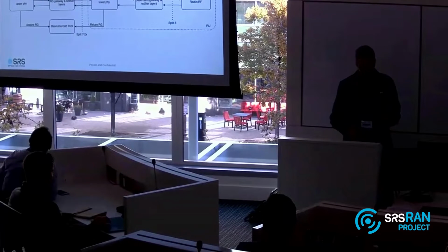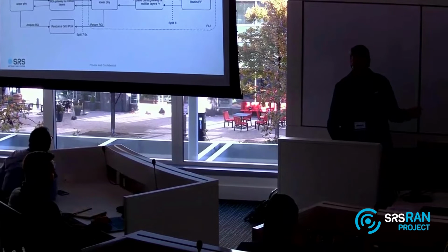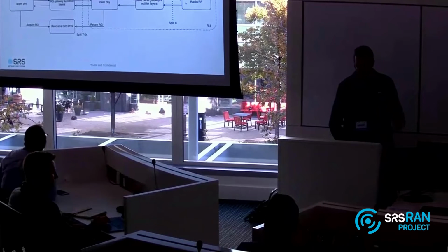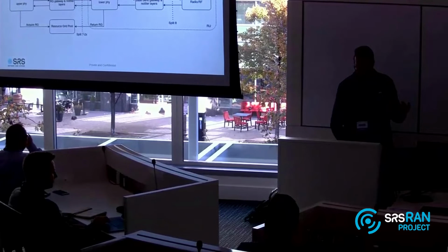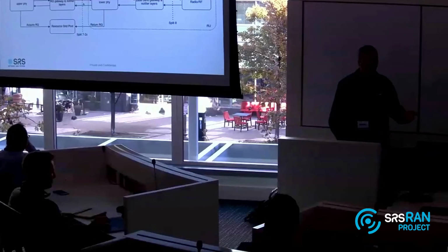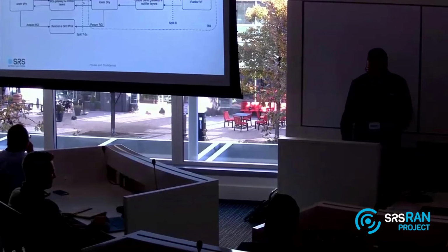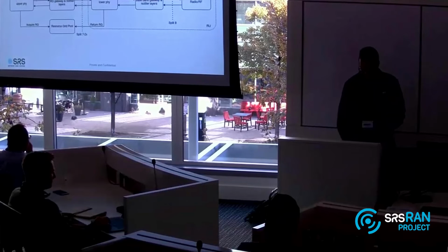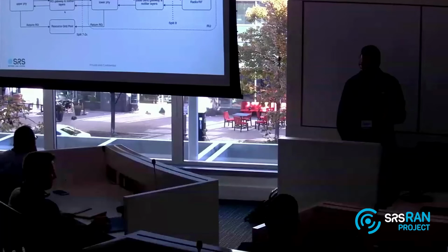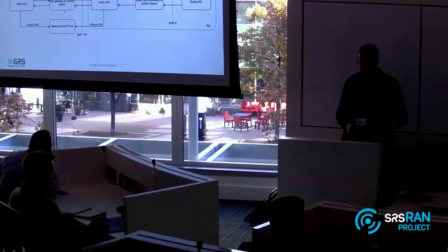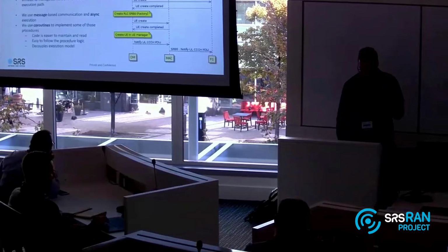The gateway then, depending on the implementation of that gateway, will deliver those resource grids to the lower PHY, and then the lower PHY will generate the samples that go to the USRP, or will deliver that to the Open Fronthaul library that will deliver that to the RU. But again, the idea here is that we use all these gateways and adapters to break the different steps.